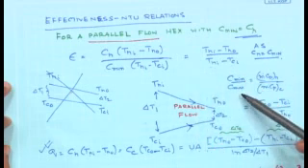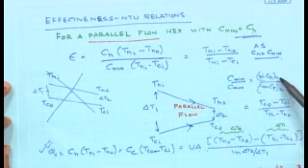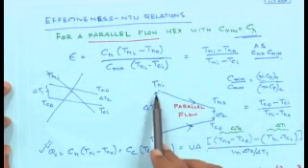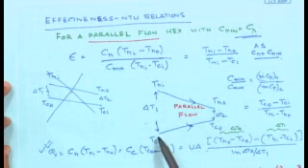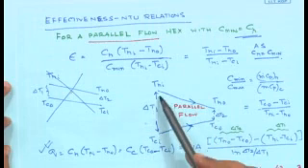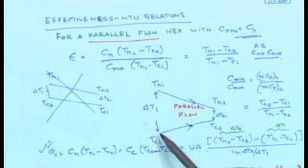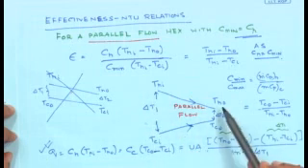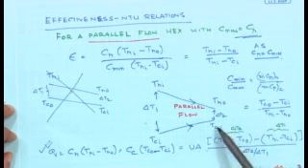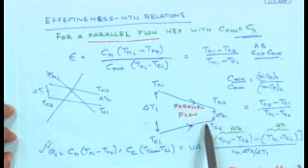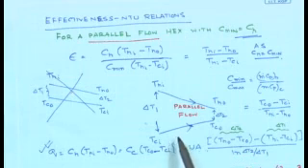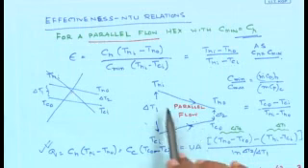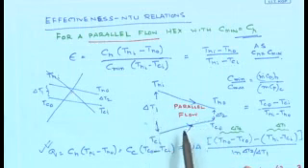The capacity ratio C minimum by C maximum is simply this. In this specific case, the hot fluid is the minimum and the cold fluid is the maximum, and for a parallel flow this is how the temperature would change. So the hot fluid would decrease from Thi to Tho, whereas the cold fluid temperature would increase from Tci to Tco. The delta T1, which is the temperature difference at the inlet, is simply Thi minus Tci, and the temperature difference at the outlet is this difference, whereas in between it's going to vary in a non-linear fashion. And we have already seen that the pertinent delta T to be used for such cases is the log mean temperature difference. So the average temperature difference between the inlet and the outlet is simply the log mean temperature difference.